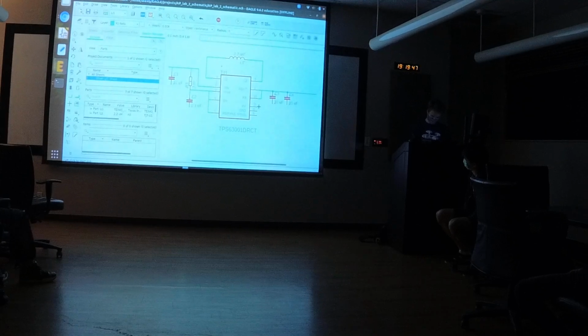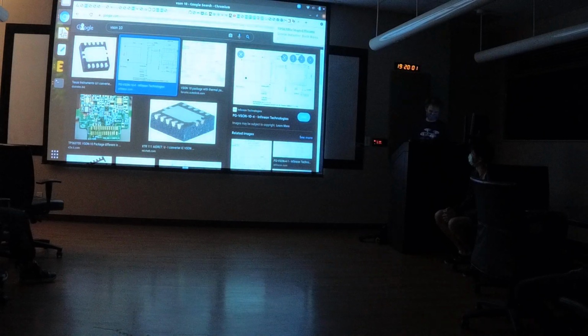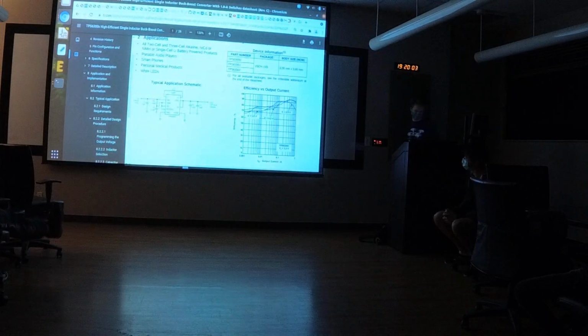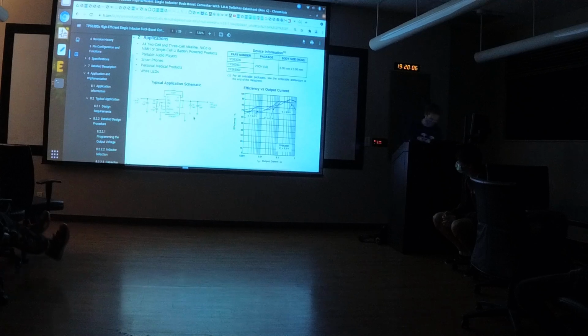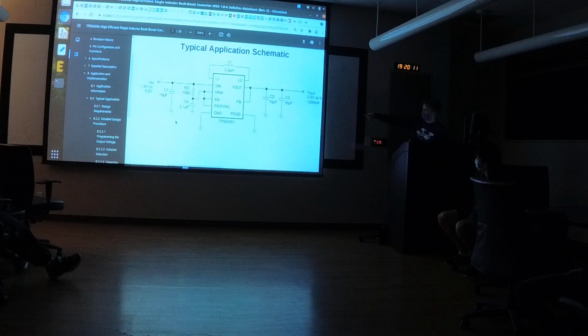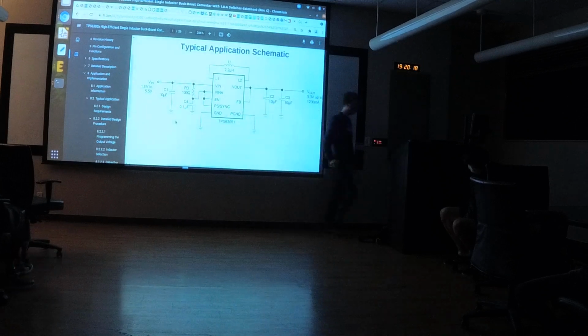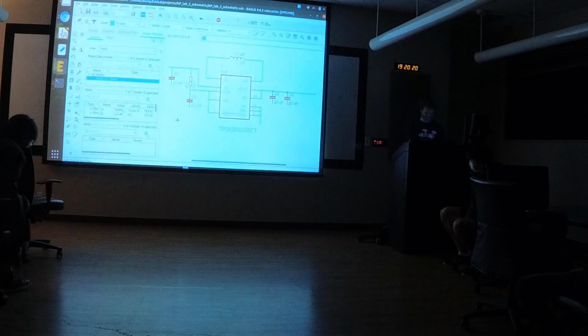So we're just gonna draw off this here. So that's a normal case. Like the bottom, there will be a plate on the bottom that you can't visually see from the outside if you set it down on your PCB, and that's usually connected to ground. For what reason? Heat dissipation. It is heat dissipation, and you generally want a good connection to ground with these circuits anyways. So we're gonna re-zoom back on this thing. So you have these weird inverted pyramids everywhere. That's a symbol for ground. So we just want to connect the bottom of the capacitors, ground to ground, and just bottom of capacitors in general. So we're going to go and add.